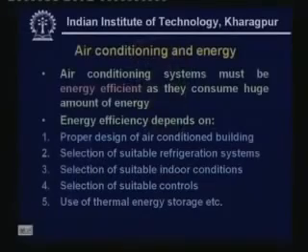And then another aspect is the use of thermal energy storage systems. The concept here is like this: there are many places where the night temperature can be very low and the day temperature can be very high. For example, places like deserts, where nights are very cold and days are very hot. So in such cases, you can use the concept of thermal energy storage. That means you can store the cold in the night and you can use part of it to offset the heating in the daytime.